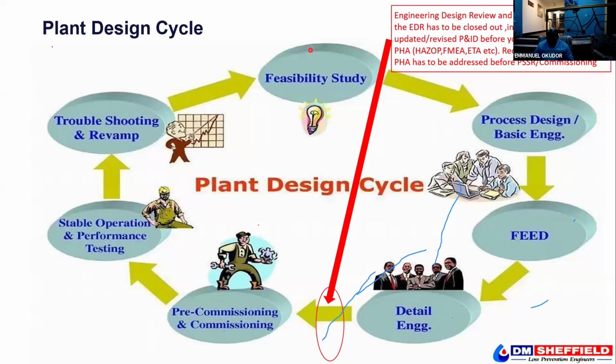It can take a certain pressure regime, maybe 200 bar. That is fine. But the rule is you have to pressure test it, and the pressure test is 1.5 times operating pressure. So when you look at that, you find out that you need to step up. Rather than 1,500, you have to do 2,500.